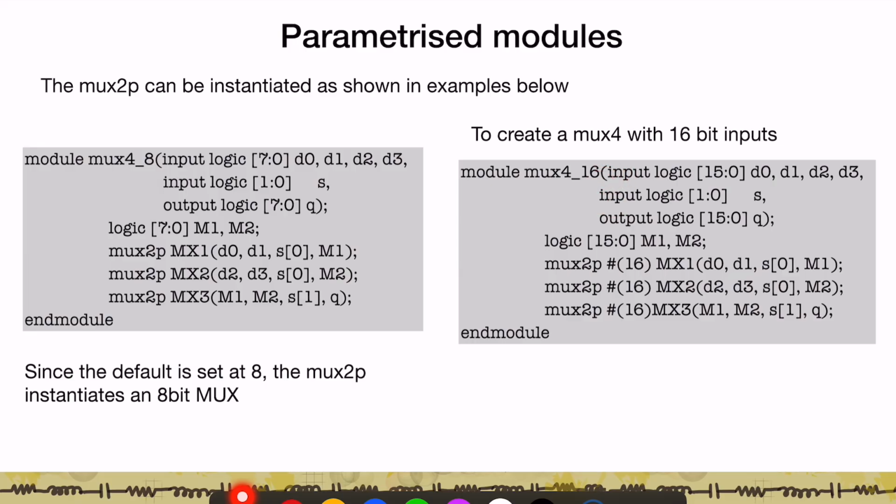So what I would do here is, again, define this MUX416. That has an input of 4 words, each of length 16 bits, a select signal which has 2 bits, and an output signal which again has 16 bits. And I'm declaring the internal variables used in the Verilog code to be capital M1 and capital M2.